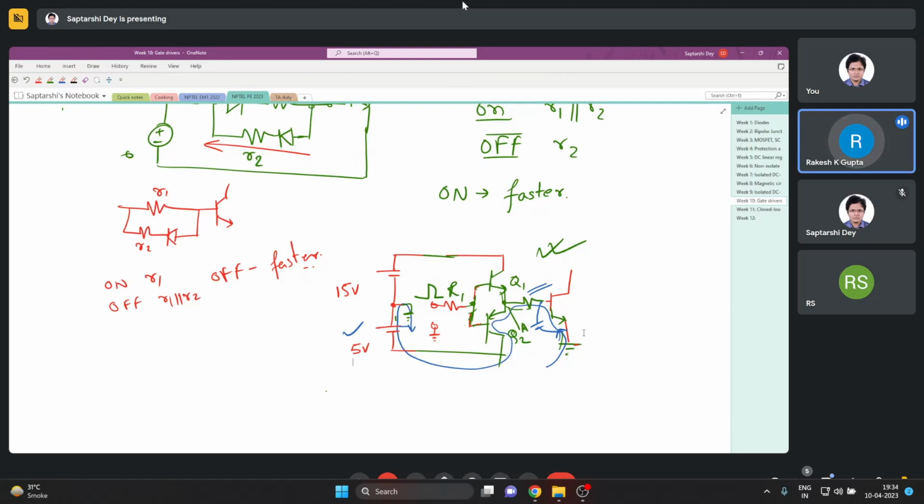Can we assume the voltage is equally divided between Q1 and Q2? Q1 and Q2 are never on together or off together. These are totem pole. So when Q1 is on, then Q2 is how much? It is now blocking 20 volt, and vice versa, minus the Q1 drop, yes.